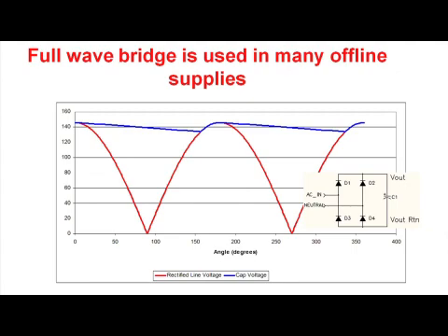The first one is a full-wave bridge rectifier, as shown in our little schematic over here on the right of the slide. It consists of 4 diodes, and as the input voltage is applied to the circuit, when the input voltage exceeds the voltage on the capacitor, the diodes conduct, and it'll conduct over this period here. And then at some point, the input voltage is going to fall below the capacitor voltage, and the capacitor itself will hold up the input voltage. And so you can imagine the slope of this line changes as the value of the capacitor changes. And then that also changes the conduction angle.